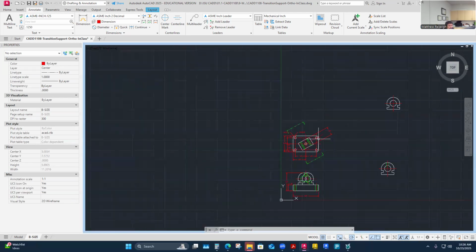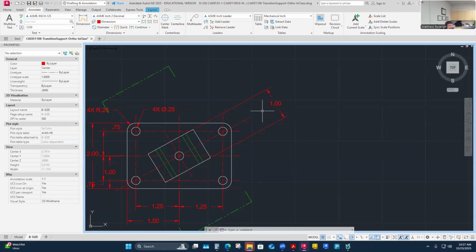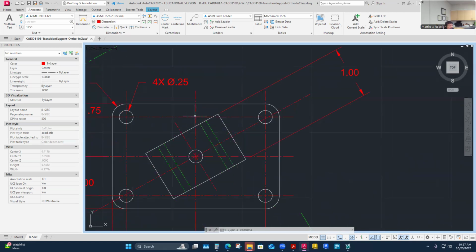Got it. And then its overall width, I think I'll pull, and that's an aligned dimension. So you might feel like this is where I'm breaking the rule. If I go point to point here it gets pretty busy, just like our last gusset did on that other part. I could actually pull from center point to point, and then worry about them from the other center point to point, the X and Y type. That's a legit way to, and some industries might make you do that.